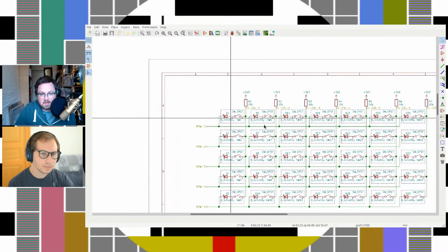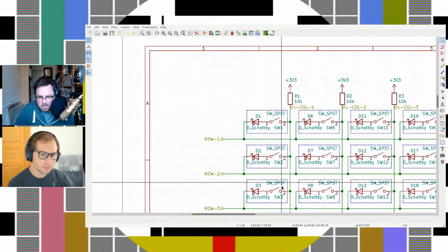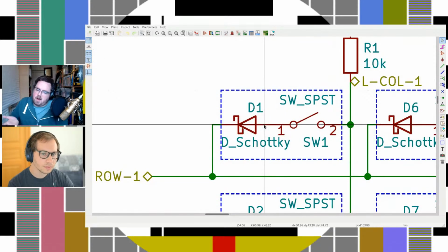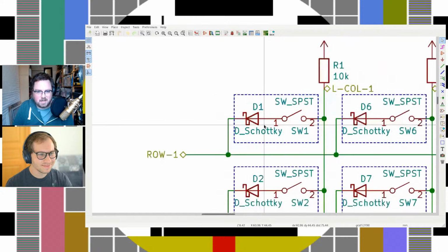Then with the diodes, the purpose of this diode is to prevent power going backwards up this way, which would cause some backflow. Then you have to figure out what kind of diode you would use, and this is going to come down to cost and performance. So this ends up going into reading data sheets or looking on the internet for custom keyboard projects. If everyone's recommending the same one, or I find some design that works and it's cheap enough for what I need, there's a lot of material out there, sort of like open source software, where it's not quite as collected in one place, but there are often people being fairly public about it, or just downloading the KiCad designs is often very easy.